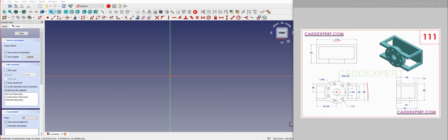and later on I will make a solid box, and then I will remove the material from this portion like this, and I will mirror it from the mid plane, which will be here. And later on, if I say in 3D, I will remove the material at this portion, and I will mirror it at other side, and from top side I will make a extrude cut to remove the material. So this is how we are going to model this part. So let's start our sketching.